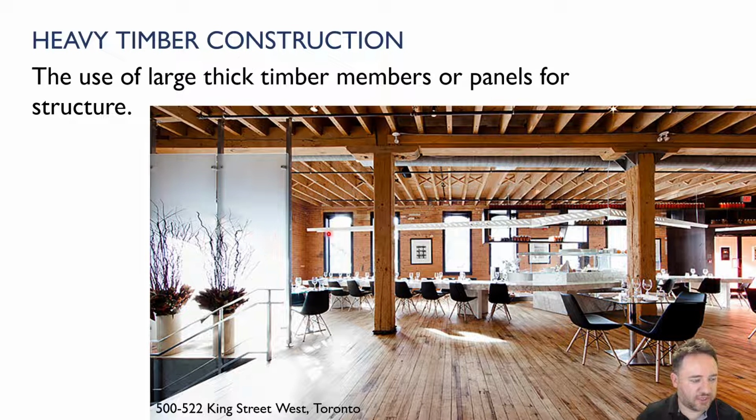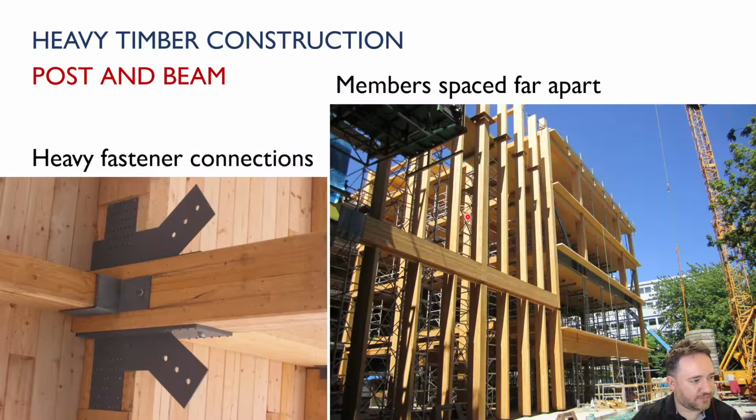So the lateral forces are taken by the external unreinforced masonry walls, and the vertical forces are all taken by the wood. And this is still what we can do today. If we exchange the masonry for reinforced masonry or for concrete, then we can still do gravity systems out of wood like this very easily. And of course, it looks beautiful. Whether this structure is going to behave very well in an earthquake, because the unreinforced masonry is not exactly sure, but it's nice inspiration for the look, certainly.